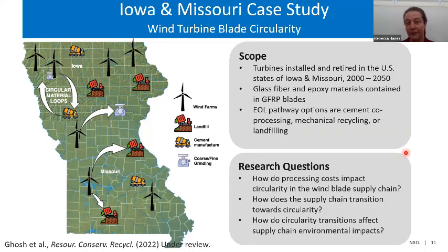primarily because, well, we know from the article they can be a problem. And we also know from a sustainability report that Vestas released in 2019 that about 85% of the materials in a wind turbine blade can be recycled, which, an important distinction here, is can be recycled, not are being recycled, just that it is possible to recycle those materials. But the big exception, that missing 15%, is basically your wind turbine blades. So size requirements, the material used, and very, very strict strength requirements on new turbine blades all kind of interact to make end-of-life processing for blades pretty difficult.